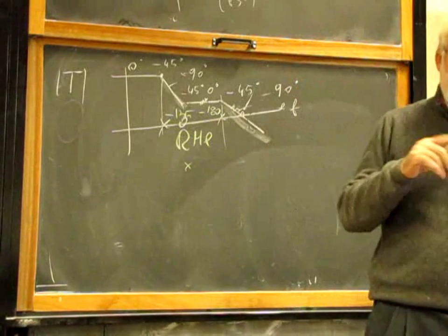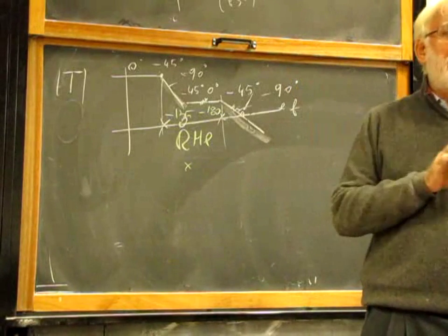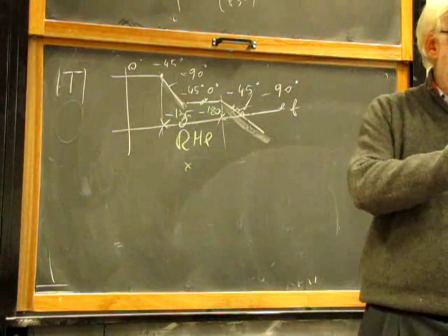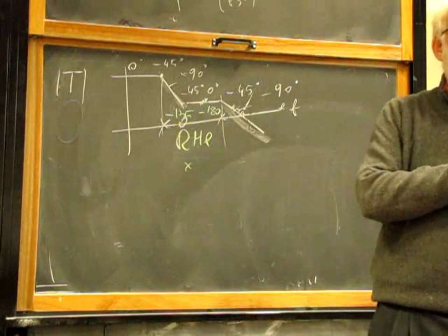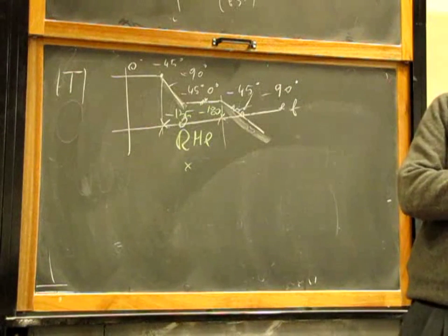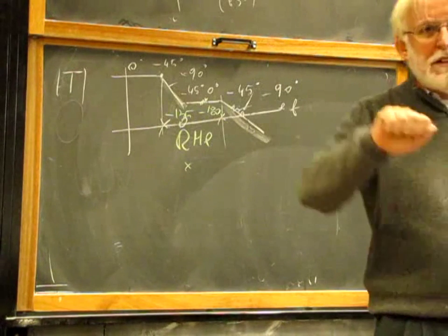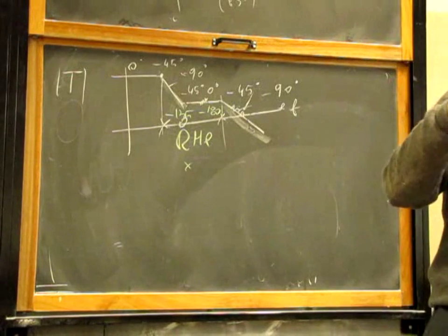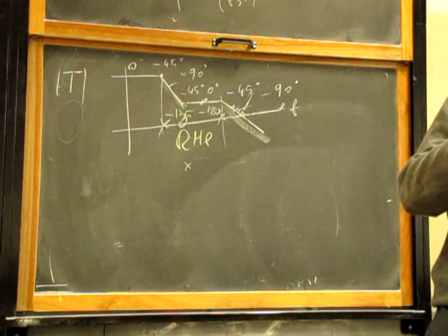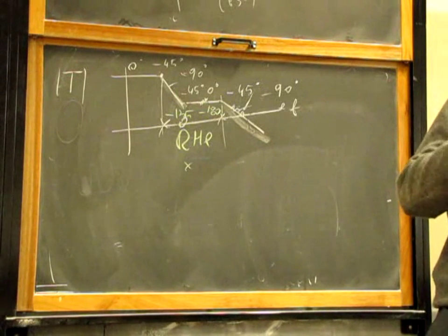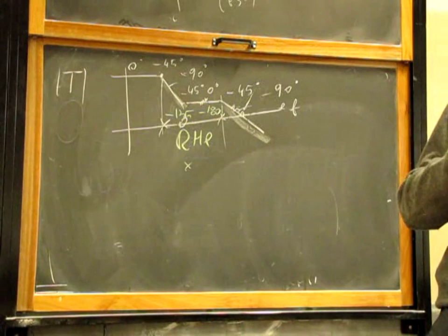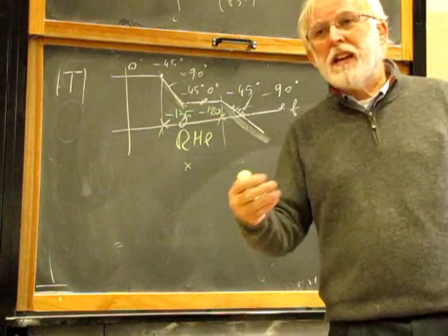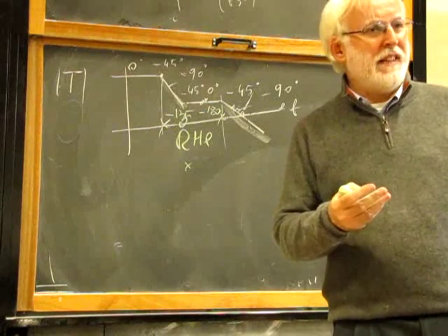Even if you have a left half-plane pole and you want to compensate it with a left half-plane zero on top of it, it works only for non-precision systems. A scope is like this. When you turn the probe compensation screw with the screwdriver, you are moving a pole, a zero on top of a pole, so you compensate for it. But this is not a high precision system. In a high precision system, just forget cancellation. If you don't like a pole, move it, don't cancel it.